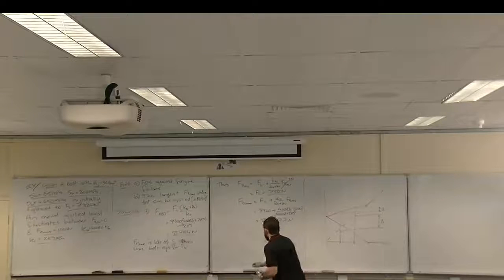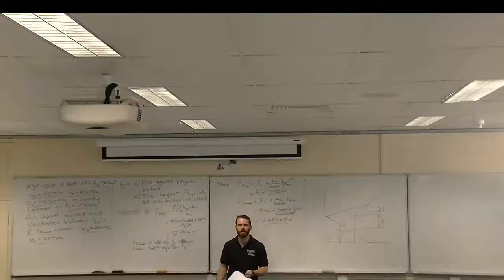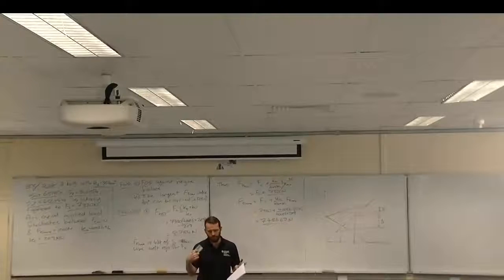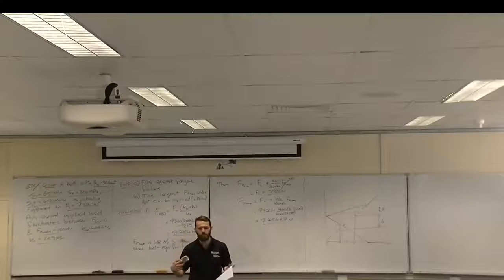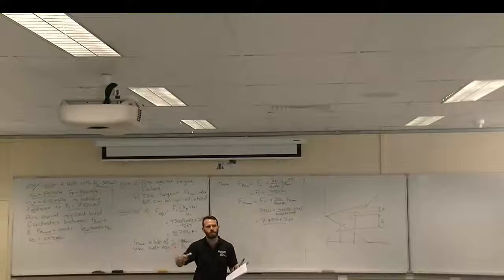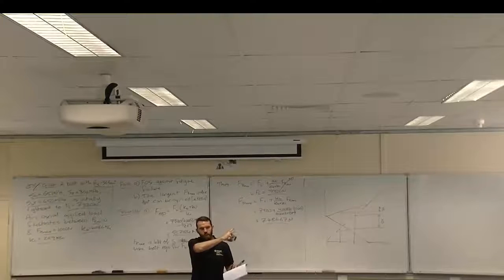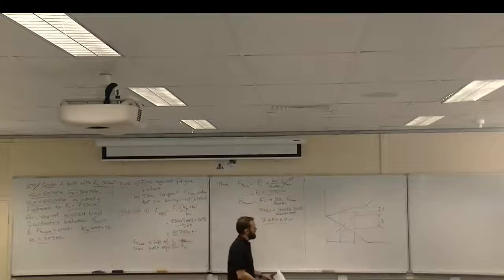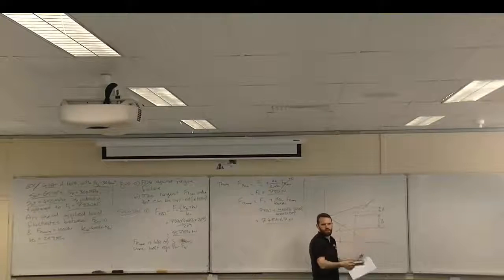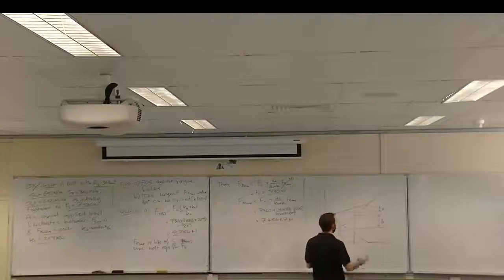Does that mean the more you tighten it, the better, or is there a point where it's not? It's not a linear relationship in that respect, but the pre-tension does help you in certain circumstances within a sort of range. So it's not just that you put force on the bolt and everything goes to hell and it's worse. The normal engineering process would say more force equals bad. But what I'm trying to show there is more force doesn't necessarily equal bad, because by putting that pre-tension on it, it changes the actual loading characteristics of the system. And so even if it's not an advantage, it's not the sort of disadvantage that you might otherwise expect it to be.